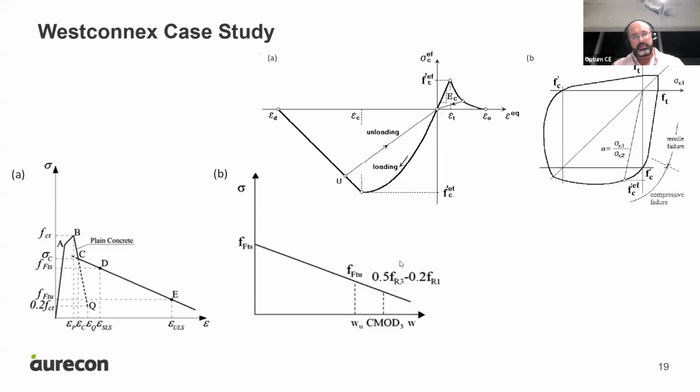And also we do fire testing as well. So we test all these mixes. I must say they have steel fibers for flexural performance, and they have polypropylene fiber for fire performance. The micro PP fibers melt and create connectivity of pores, so the expansion of vapor is able to escape and avoid spalling. PP fibers in our shotcrete were about 1 kilo per cubic meter of micro PP fiber, and in the segments in the order of 1.5 kilos of micro PP fiber.